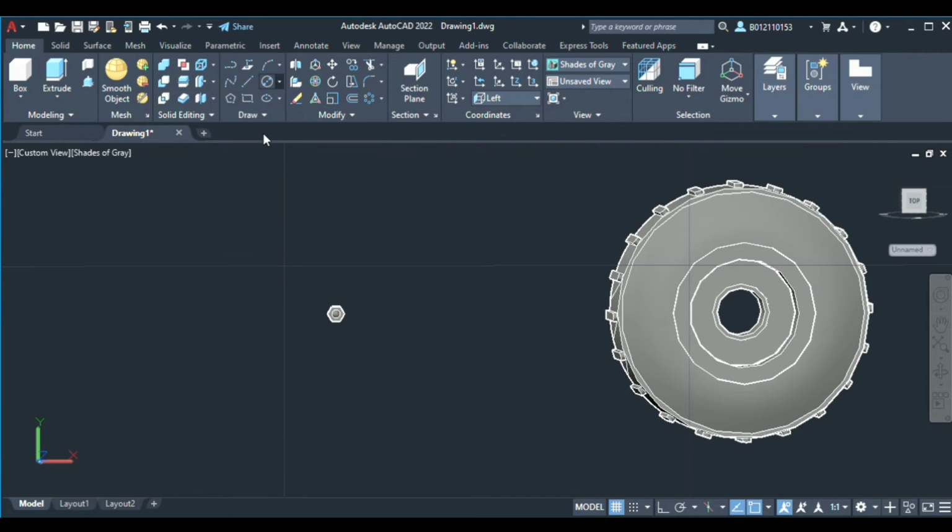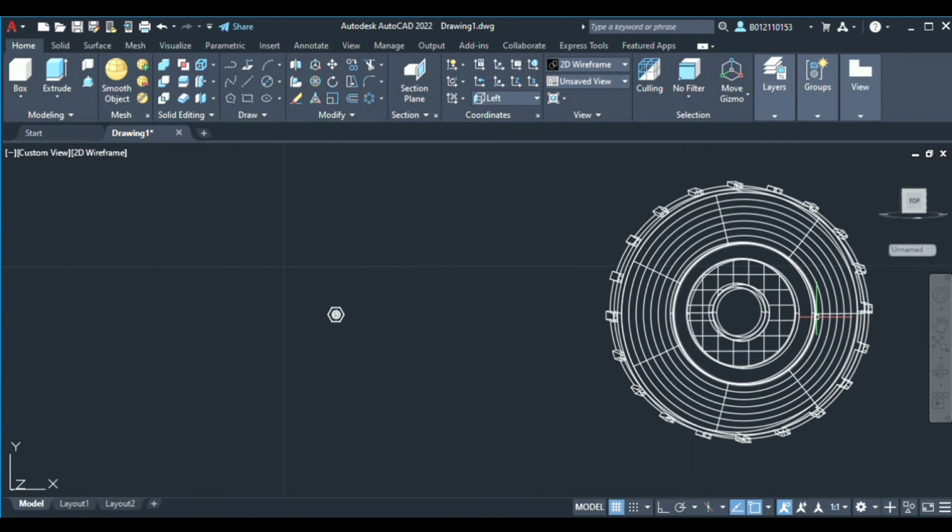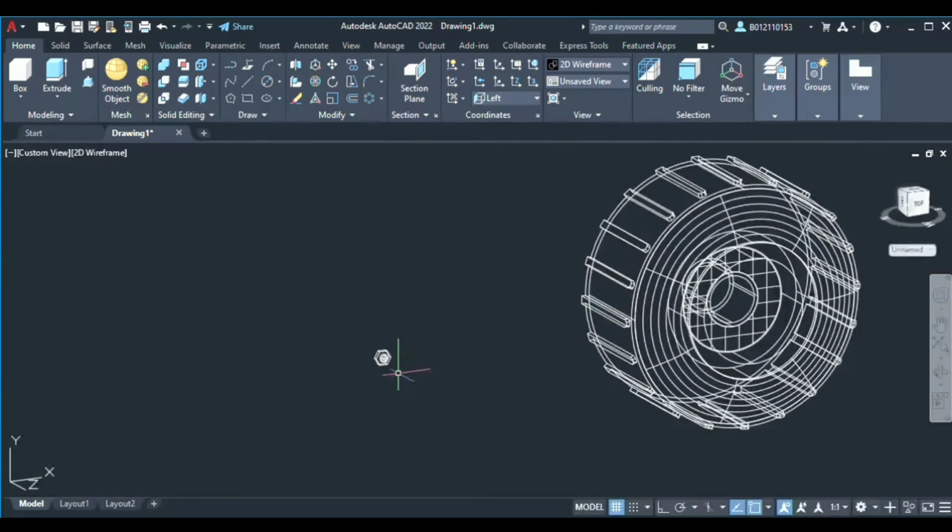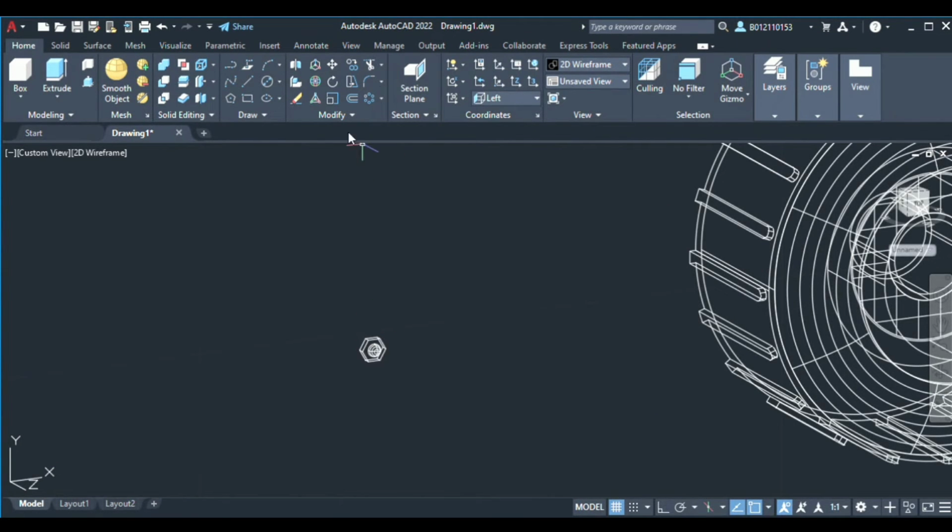First we need to make the diameter of the circle here 3.5. Alright, there's the circle right here. Sorry, let's make it 2D wireframe. Okay, there's this circle here. So then we move this thing here, the center. Alright, first, let's not take that point, we need to take the back point here, the center, keep the back point here.